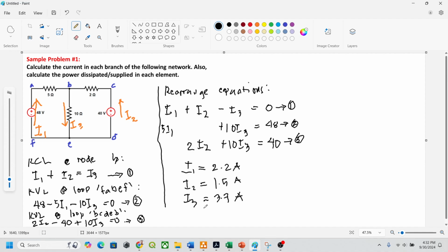So it is a sign now that you're doing your equations right. Okay, so if at one point in your node the KCL doesn't hold, there must be something wrong with your KVL equations. Okay, so you have to take note of that.